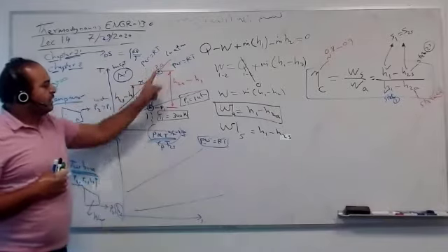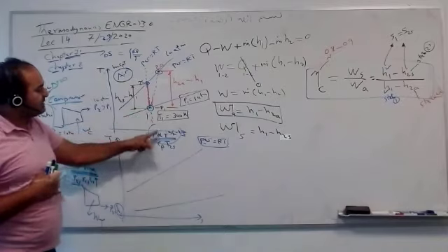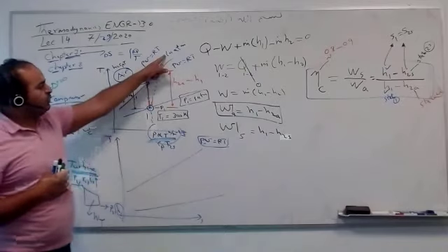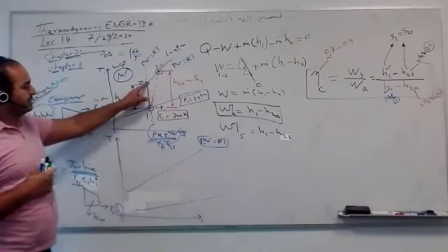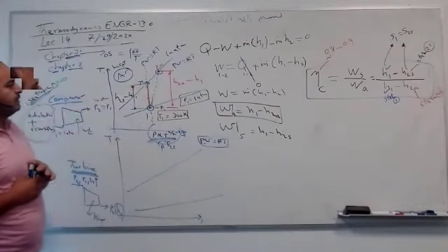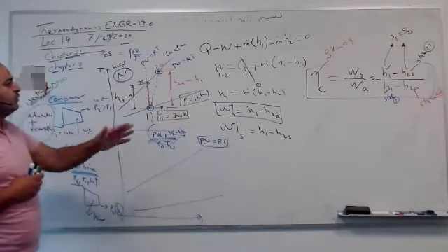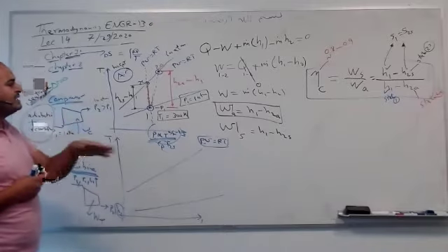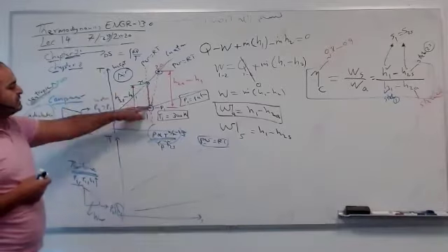Pressure 2 you have. You can get T2S from this equation, because you have P2S, P1, and T1. You can get H2S, V2S, U2S, everything at 2S, because you have the pressure and you have the relation, and it's the same entropy as state 1.